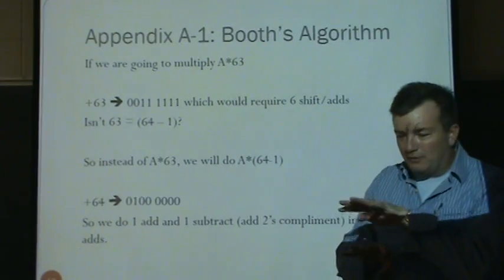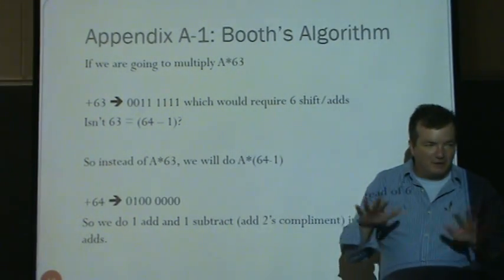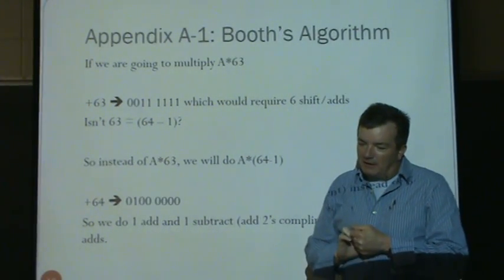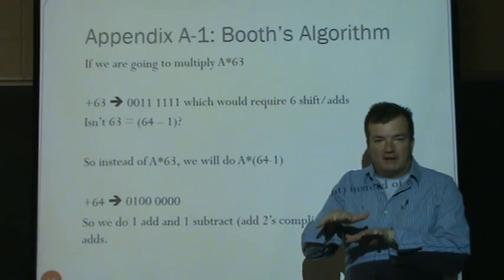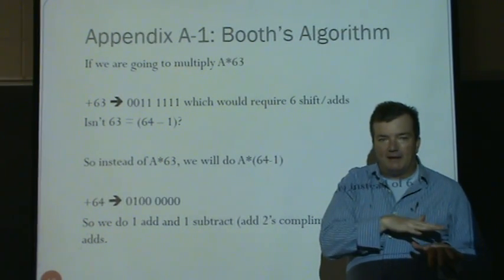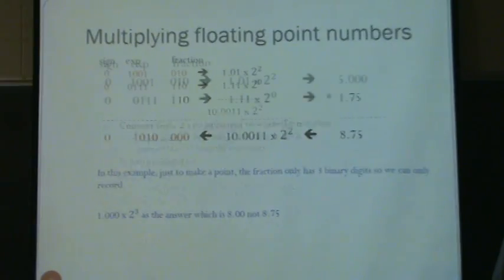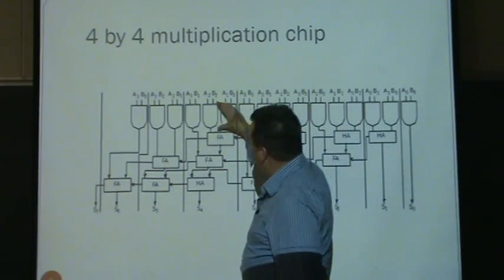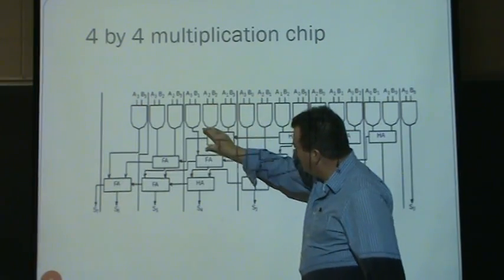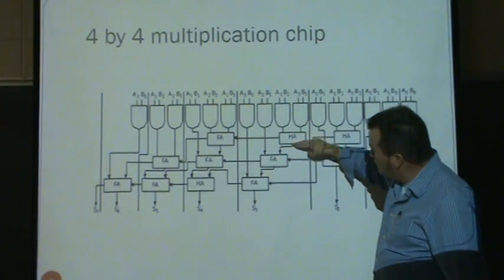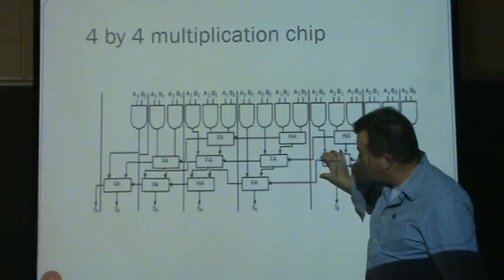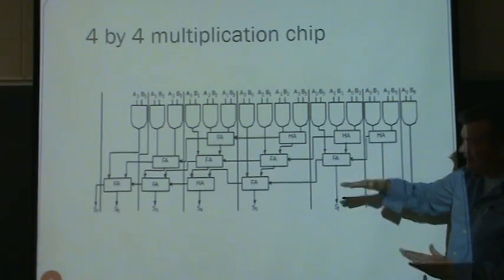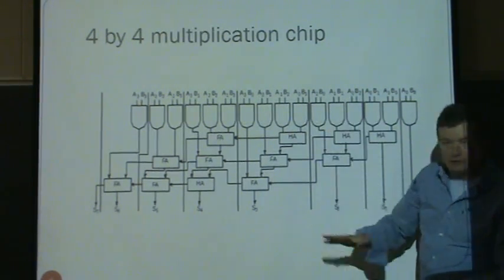Suppose you had two 32-bit numbers, and let's look at unsigned, no positive or negative. It doesn't make a difference once we add positives and negatives. If you were going to multiply them together, how many possible times would you have to do an add? Here's 4 bits times 4 bits. We have one layer of results, these AND gates. They feed into a second layer, and then those results, when you're adding numbers together, feed into a third layer and a fourth layer. So for 4-bit numbers, there are 4 layers of results. The more layers there are, the more time we have to allow.